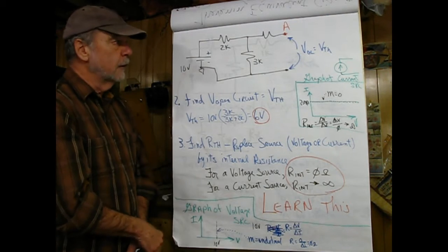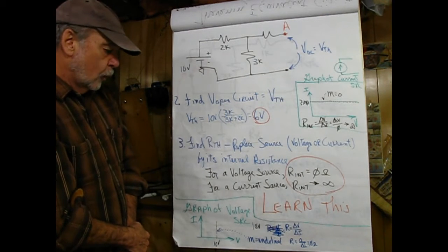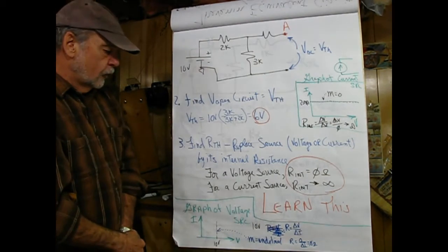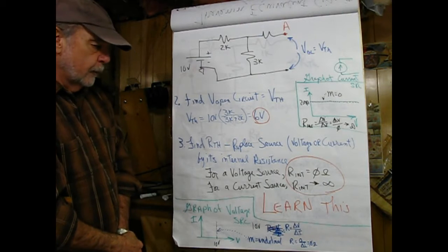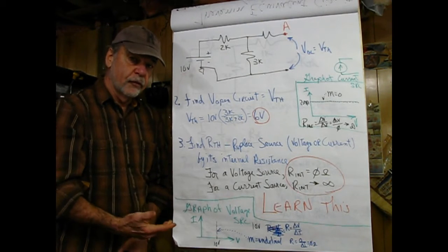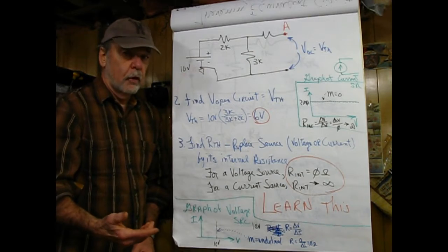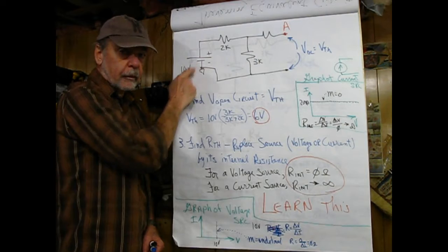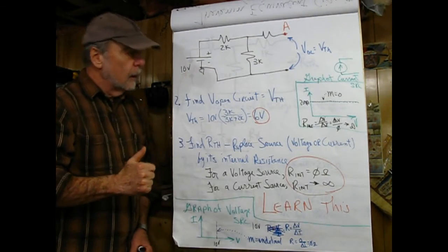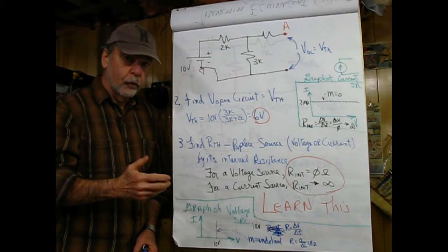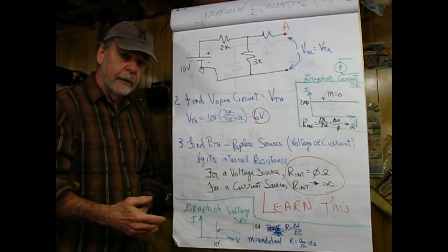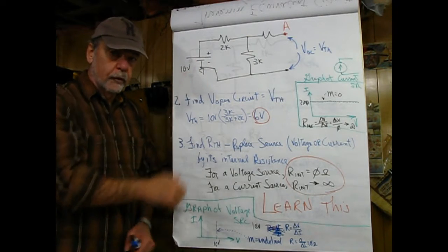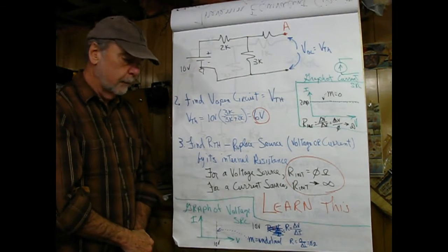That is the equivalent circuit of this network, and what we have to do is look into it. Before we can do that, we have to take into account how we handle the sources. It's always wrong to take an ohm meter and check a circuit with the supply active. Always wrong. The ohm meter has its own source, and it generates its own current, and then the internal electronics turn that into resistance. If you have an external voltage or current source, it isn't going to work.